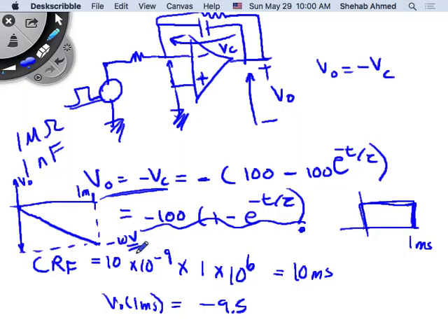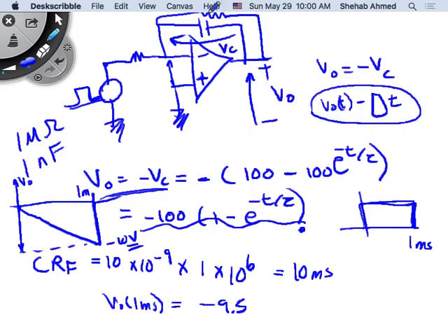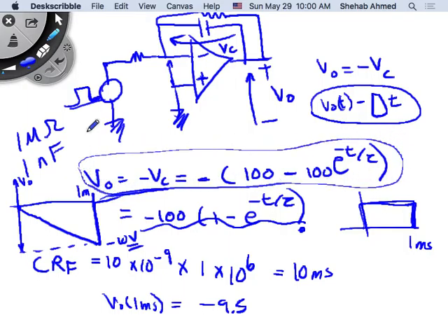And then, if the pulse was brought down to 0, still without the feedback resistor, the output voltage goes down to 0, because the output voltage was what? A constant times t with a negative sign. The output of t was this in the case without the resistor. In the case with the resistor, it's this.